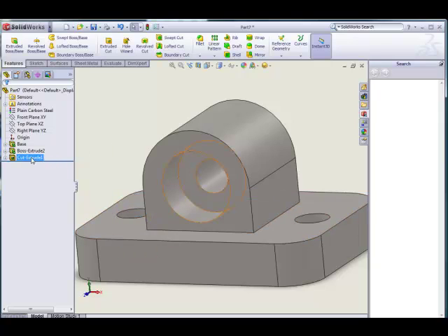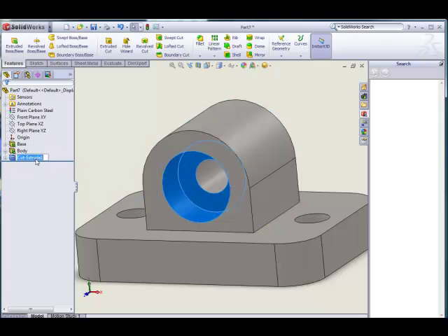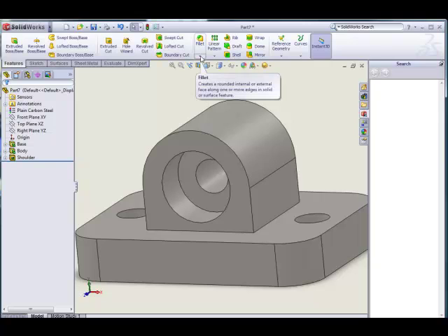We will rename it now, so we'll rename the body, select the body, press F2 and rename it. Rename the cut, that's shoulder, so select the cut, press F2 and type in the name. So we can now add more applied features to it to finish off our object. We have to add a chamfer and a fillet. So underneath fillet you can see a little arrow. If we click that, we can see fillet and chamfer.